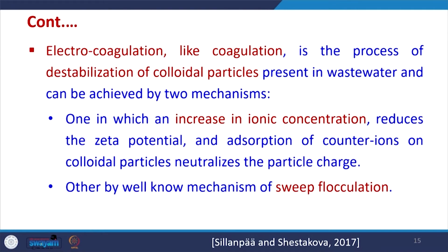Electrocoagulation, like coagulation, is a process in which we destabilize the colloidal particles present in the water. We have studied this in detail during the coagulation and flocculation section: the colloidal particles which are not able to settle down can be destabilized.